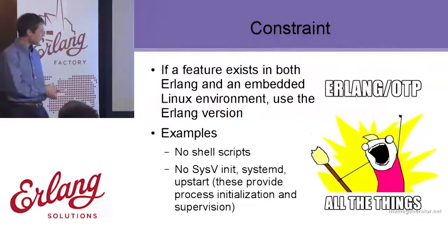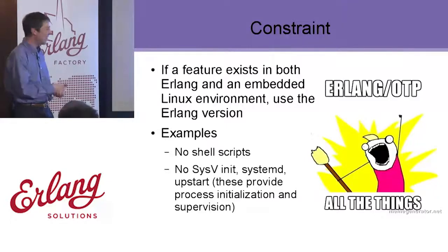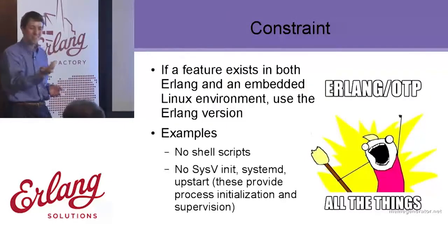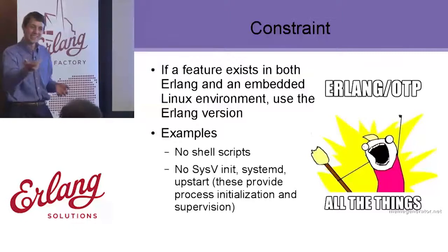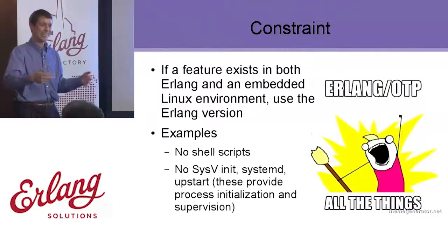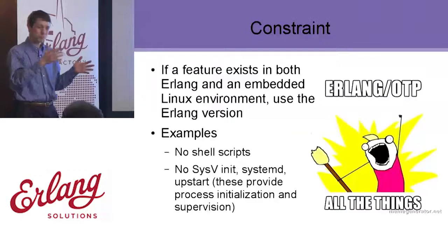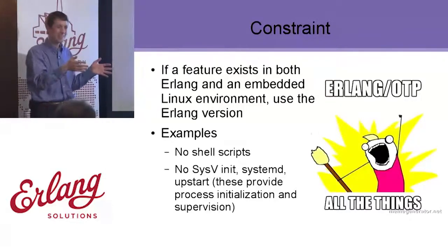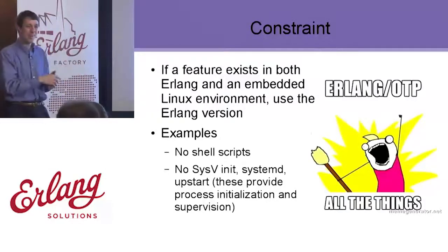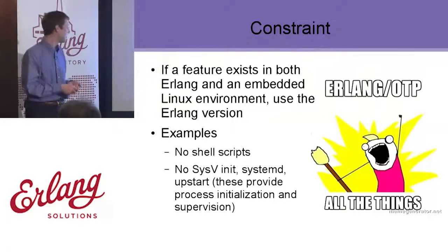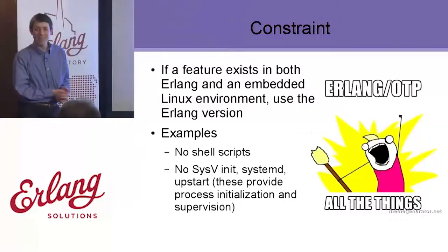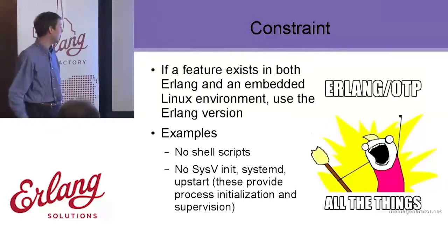And there's overlap. And this came to kind of a crazy decision: really, should I have shell scripts and init scripts at the beginning? So on these embedded Linux projects, how do you start your app, right? The traditional way is to use really simple System V init scripts to start your programs up. And there's actually some supervision that you can get in with these init programs, and especially now with systemd, which is another common embedded Linux tool.